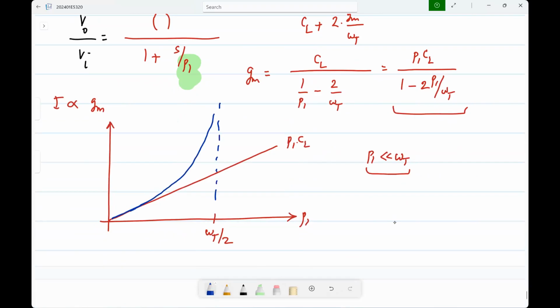Okay. This is in general what you expect with any circuit, right? Given a process, you try to make a circuit for higher and higher frequencies. It could be amplifiers for higher and higher bandwidths, latches for higher and higher data rates. To do anything, what happens is at very low frequencies, the power dissipation will be proportional to the frequency of operation. Okay, some things have to keep constant. In this case, the noise happens to be constant. Okay, so if you make an amplifier for some bandwidth, right?